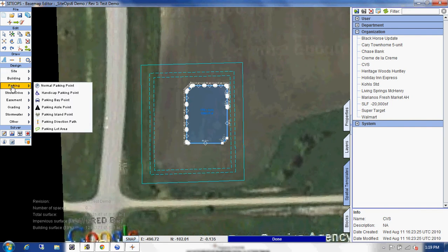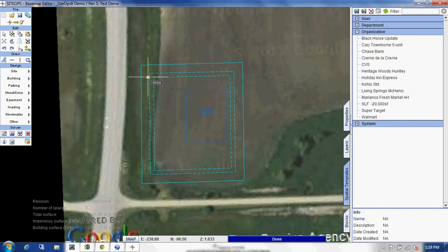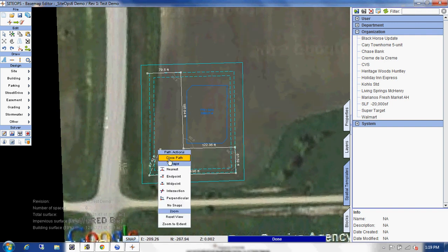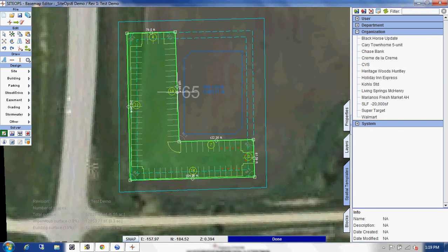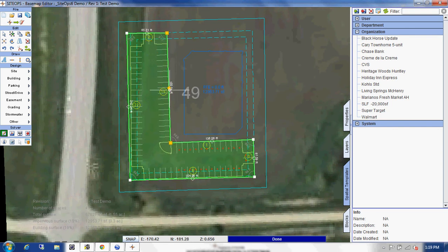And I've shown this in some previous videos of how this site planning software works. I'm just going to show something really quickly here. It's covered in a little more detail in some of the other videos. But what I've done is I've just drawn in a parking lot, and then when I hit the site planning solver, it automatically drafts in all these parking spaces.